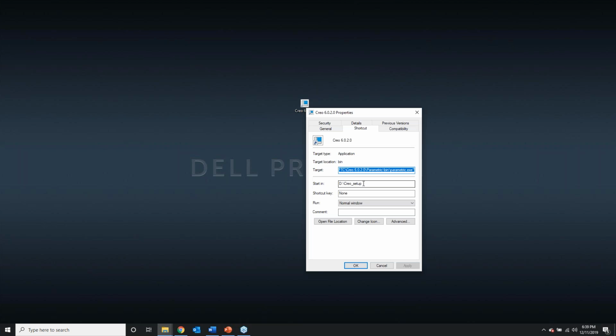Okay, so there's a few ways that you can handle your config.pro. I know a lot of administrators will put it in the installation folder under the text folder. So they will run a batch file. It will copy it from a mapped drive on a server, and that's how they enforce users to use specific settings. So they can use a config.pro or a config.sup. I'll quickly go to my sup file and talk a little bit about that as well.